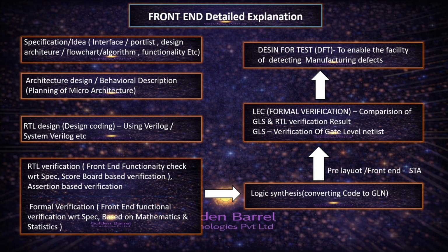Then after that, there will be DFT, design for testability. Why DFT? What is the necessity? After manufacturing, this VLSI chip may contain millions of transistors connected together. If there are any connectivity issues or defects after manufacturing, it is not possible to detect those manually. So we need some mechanism or technique after manufacturing to detect the defects and any connectivity issues in the IC.